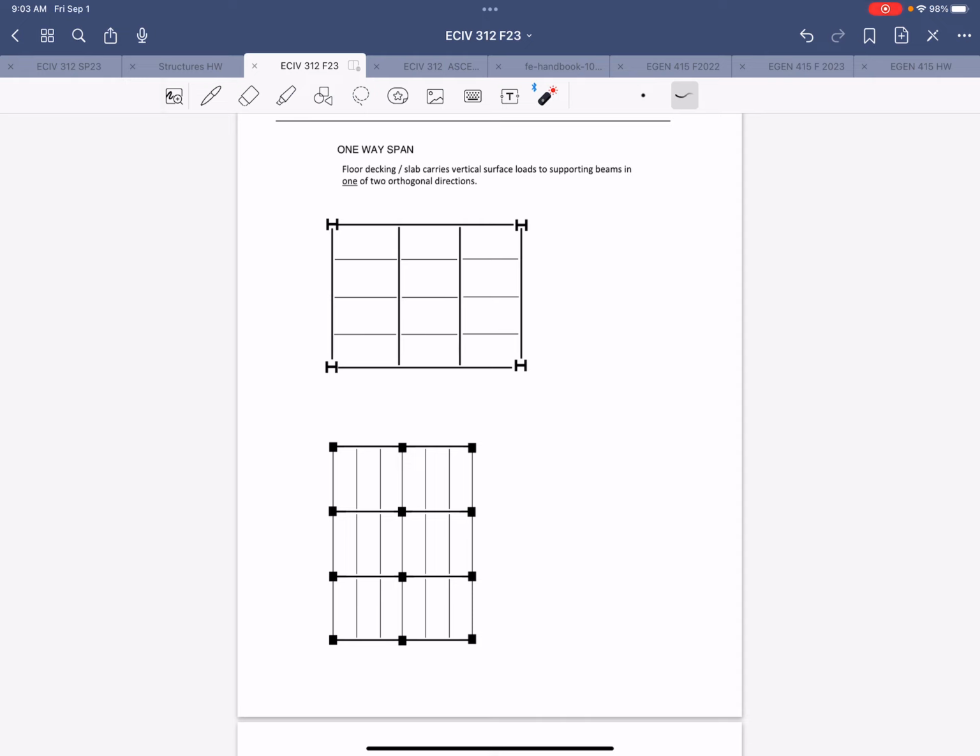And then also the fact that the girder lines are a little more bold indicates that that's a beam that supports other beams, or it's further down in the hierarchy of the load path. So because these first level of beams are spanning left to right on the page, we can conclude that the floor span, or the span of the surface, is perpendicular to those beams.